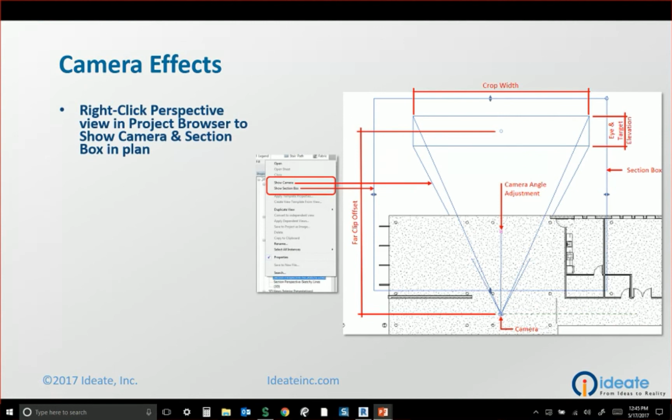If you actually go to create a perspective view, you want to look at the properties of that section view. So you just go to the section view, look at the properties, and turn on the section box. If you don't do that, then you don't get the option to show the section box and actually manipulate it, okay? So basically a section perspective is not just a feature in Revit where you go to the view tab and hit section perspective. You've got to do the section, turn on the crop box, and then you can actually create the section perspective.